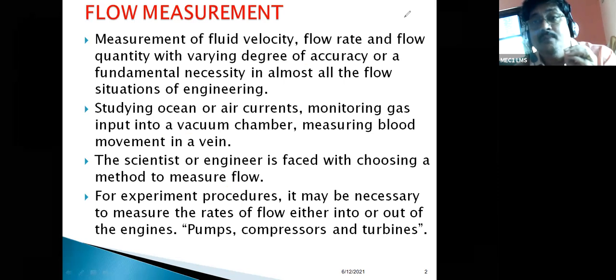The flow rate is very important. We have to fix the flow rate according to the amount of heat delivered or dissipated from the radiator, and send that amount of flow through the pipeline. Then automatically the radiator will cool.